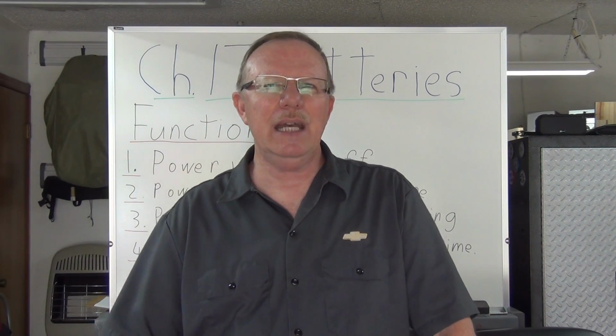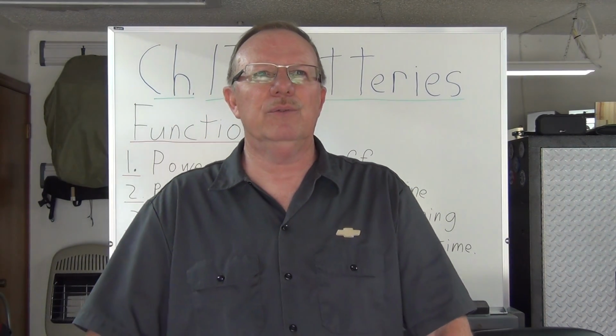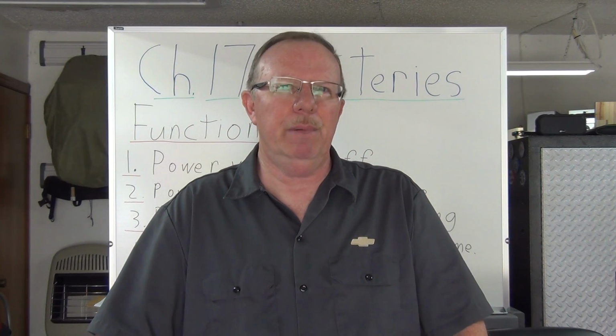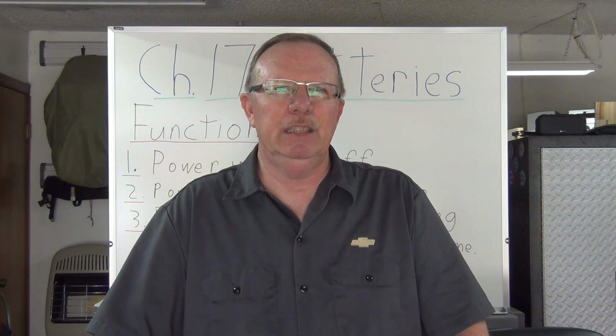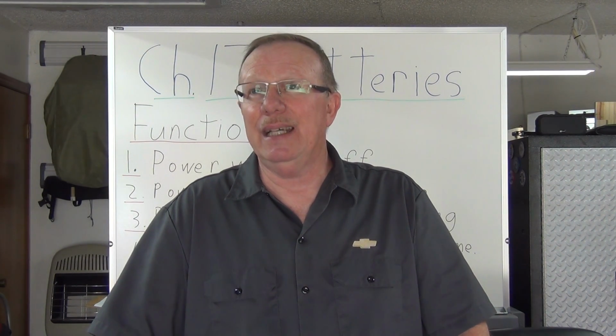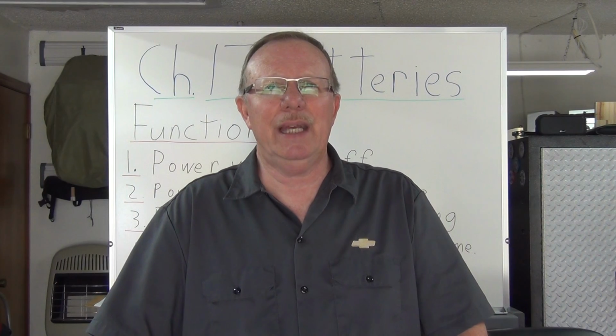Okay. So, power when starting when it's hot. Power when starting when it's 0 degrees outside. Since a battery is a chemical reaction, it's sensitive to temperature, and its ability to create voltage and amperage is relative to the temperature of the battery. That may be one reason why they put some of the batteries inside the cars now. A little bit more stable environment than underneath the hood. Under hood temperatures get pretty hot, especially on a hot day, and so there's a couple reasons why they put them inside the car, but one of them has to do with the environment that it's in mainly.